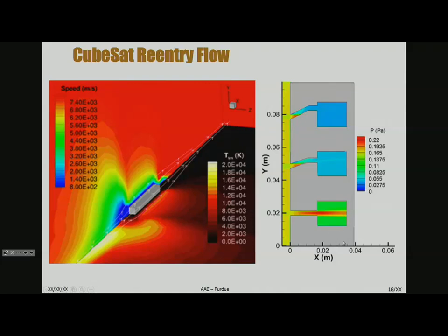So we came up with these sort of settling chambers where particles would fly in, they'd collide with the back wall, and they'd diffuse within this settling chamber. So their temperature would be equal to the back wall, or about. The velocity would be pretty low because it's about 0 in here. It's 8 kilometers per second out here, but within here, after it collides, it's about 0. And things don't change super rapidly in these settling chambers. So that way we're able to get a very good pressure reading in here.